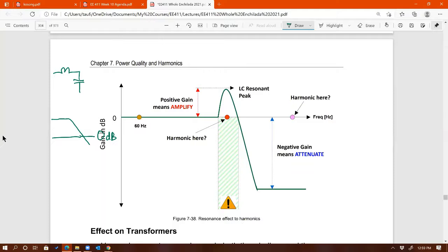when the load is heavy, close to fully loaded, the damping ratio is very small. So then this will have a peaking effect, as you learned from 302, right? A very low damping ratio means you're going to have a peaking effect, percent overshoot. That's basically a gain. Actually, this is not 0 dB. 0 dB is right here, so a gain of 1, and then you are introducing a gain if you have a peaking effect, right? Okay, so that's what I have right here. That's the drawing for the second order system with peaking effect.